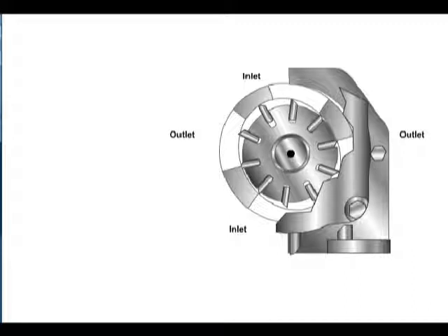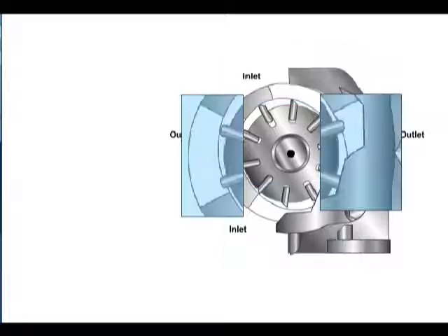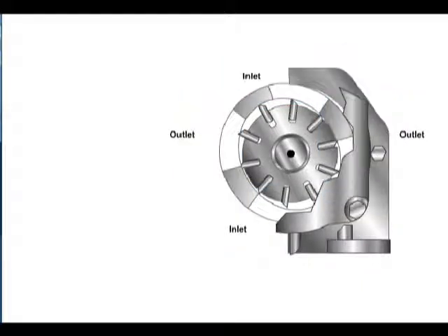To compensate for this, the ring in a balanced vane pump is changed from circular to cam-shaped. With this arrangement, the two pressure quadrants oppose each other. Two ports take fluid in and two pump fluid out. The two inlet ports and the two outlet ports are connected inside the housing. Because they are on opposite sides of the housing, excessive force or pressure buildup on one side is canceled out by equal but opposite forces on the other side.